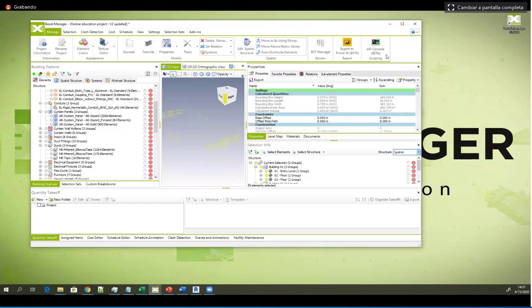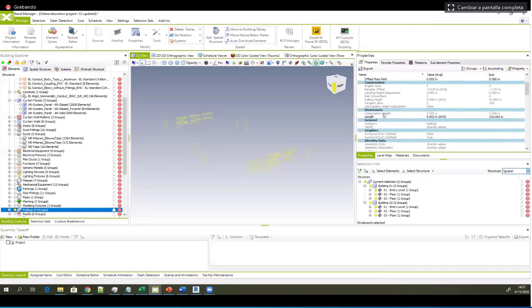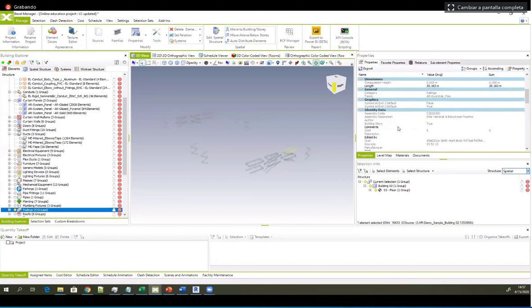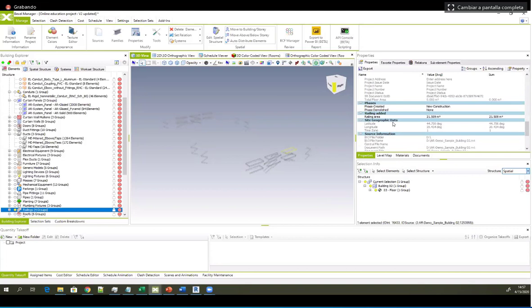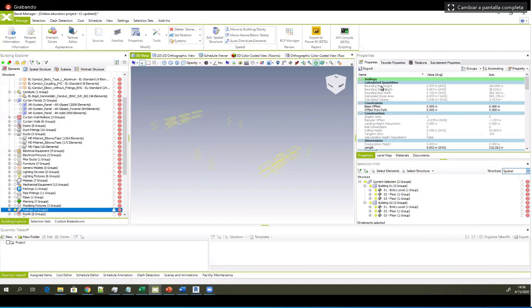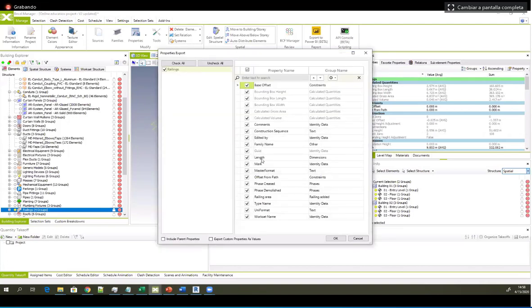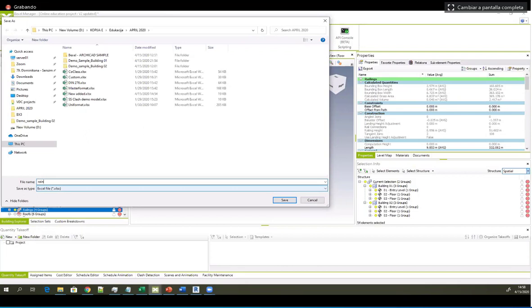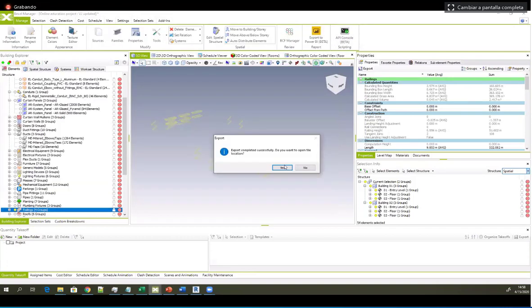So if we hit OK, and now go to the new group, which will be called railing edit, we see the railing area and we see the area of these selected elements. For each of these, we can check the area, which is calculated by the Bexel manager. And of course, we can select all these elements which are currently visible in our screen and export the properties from selected elements into Excel spreadsheet again and save it. And this is the way how you can exchange this information.